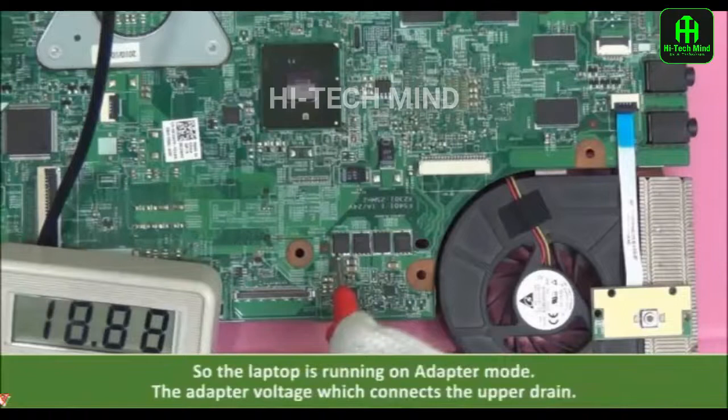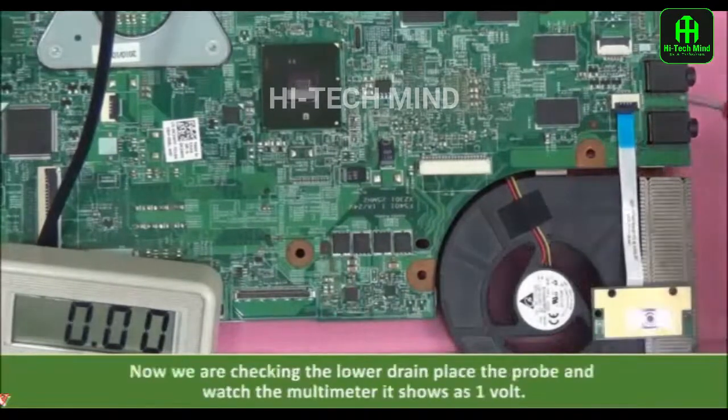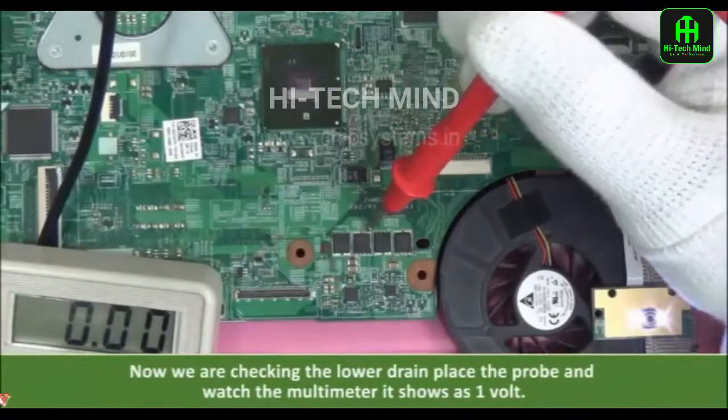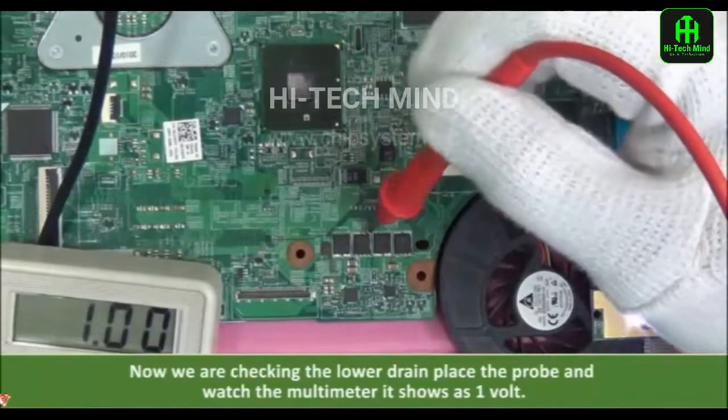So the laptop is running on adapter mode. The adapter voltage connects to the upper drain. So the upper drain voltage is present, and then check the lower drain voltage. Now we are checking the lower drain. Place the probe and watch the multimeter. It shows the reading 1 volt.